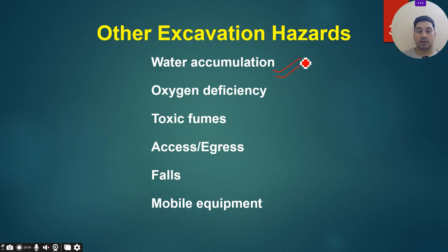So that water you have to remove. First, you have to check the utility. Second, if there is water, you have to take it out with a pump to make sure that there is no risk or hazard from the water accumulation.